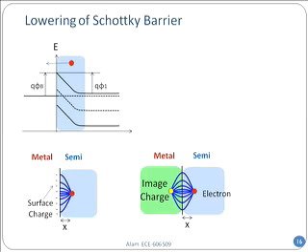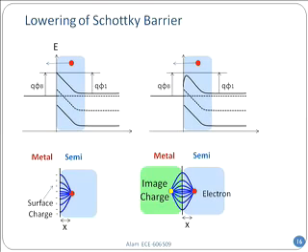As a result, effectively speaking, the red electron will get an extra pull to pull it out of this semiconductor. As a result, look at the barrier. When you combine this extra electrostatic pull, it is as if the barrier has gone down effectively, because the electron can pass out from here a little bit easier. And so that's why that barrier is a little bit lower than what you would have otherwise thought. If the other side was a semiconductor, then you wouldn't have this effect.